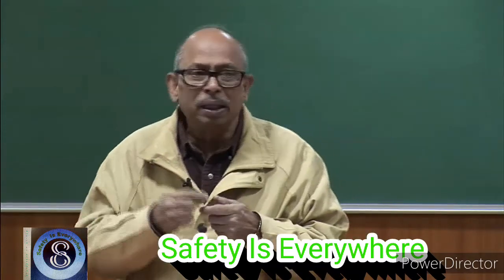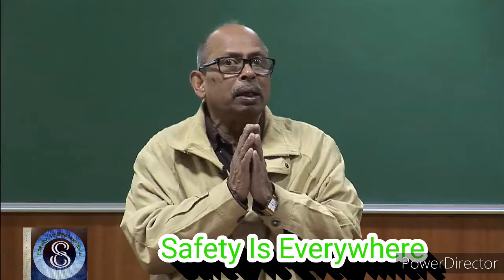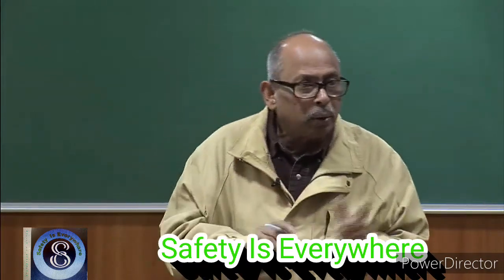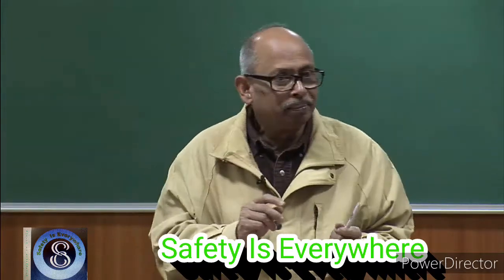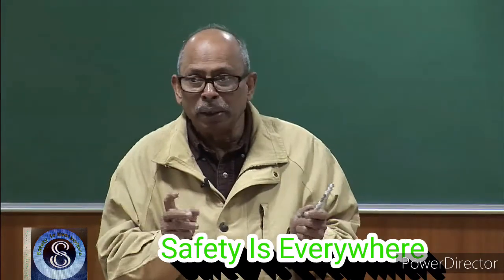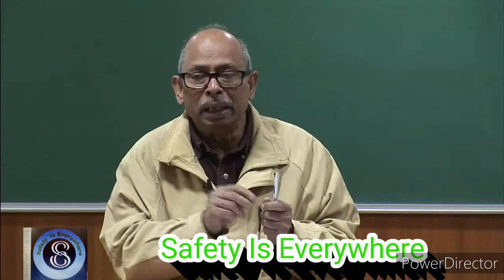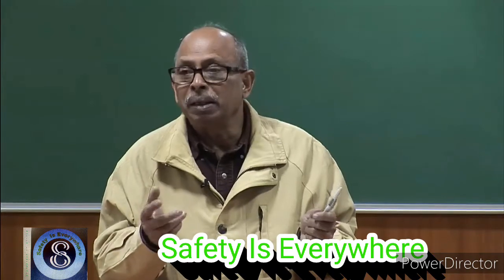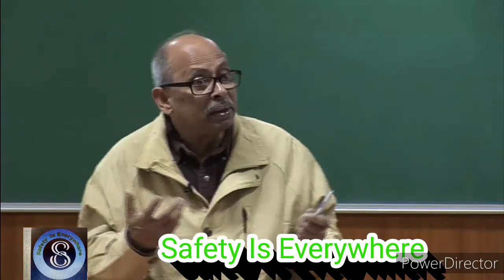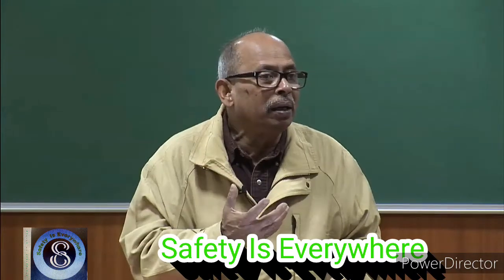If you see the materials also, for example, I was talking about that wood thing. If you cut pieces of wood and spread them, that's important. That's why fire load per unit area is important, density. If you have pieces of wood, that would burn faster, that would catch fire, with large surface areas. While if I have a log, it doesn't burn the same.